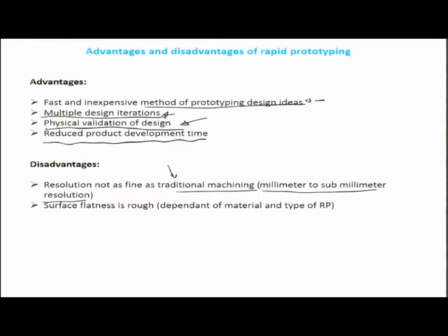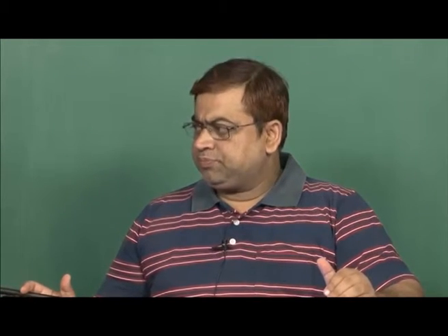amount of surface finishing. Some of the tools like electrochemical machining and electrodeposition used in synergism, with some synergy, would be able to realize as fine surfaces as about 100 nanometers plus minus average roughness values, as pointed out in the literature many times.